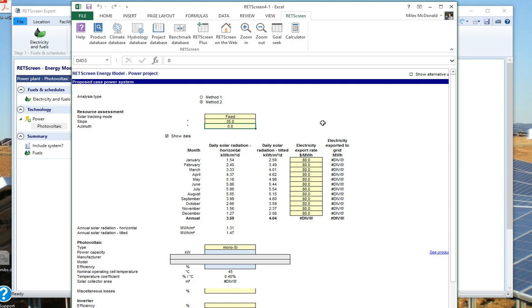What about, let's go to Azimuth. We're pointing directly due south. There's a big honking building just to the east of us, and it throws a shadow. Do I want to be pointing due south? Well, we're not getting anything in the summer or in the morning. So let's point it a little more towards the west.